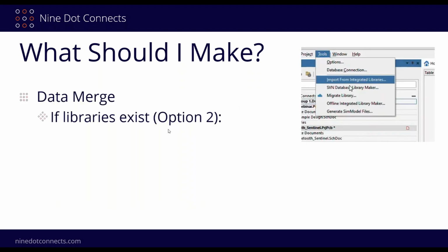The other option that you have, and I had forgotten about this, but it has been in Altium for well over a decade, is that you can create a database from integrated libraries. This is the second one. What I showed over here is that if you open up a new DB lib and go to tools, then import integrated libraries, so it has to be an integrated library, you can go through the motions of turning it into a database form. It's going to put it in Microsoft Access, so you'll need Access in order to open it, but you can certainly work from that as well.